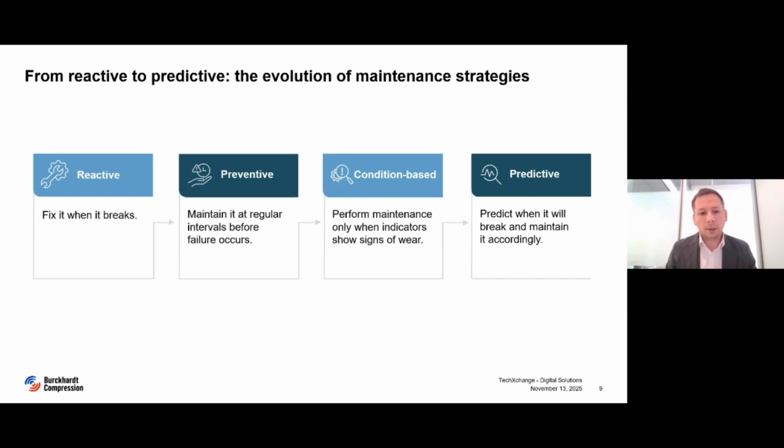But the second big trend which is going on is related to the first availability of digitalized data about performance of components, with the implementation of condition monitoring techniques and advances in pattern recognition, artificial intelligence. These two aspects allow, in an automatic way, to first identify failure mode, and second, with a certain accuracy, make a prediction how long compressor or component performance will remain acceptable for operation. That can bring us to much better and more informed decisions.